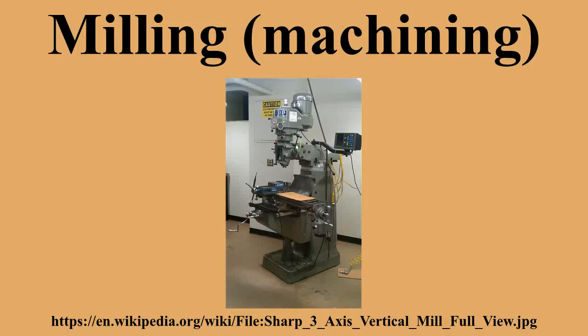Gang milling was especially important before the CNC era, because for duplicate part production, it was a substantial efficiency improvement over manual milling one feature at an operation, then changing machines to cut the next operation. Today, CNC mills with automatic tool change and 4 or 5-axis control obviate gang milling practice to a large extent.